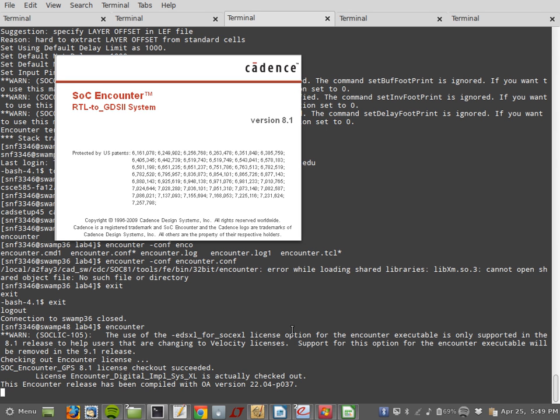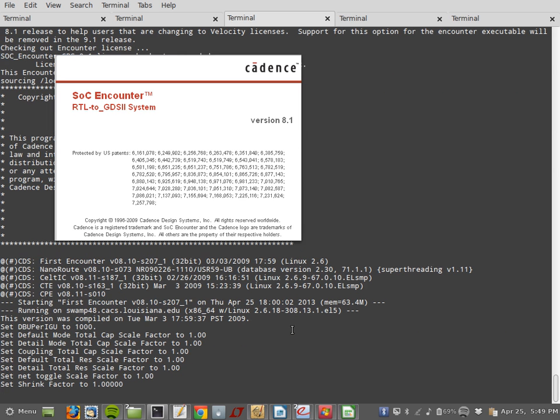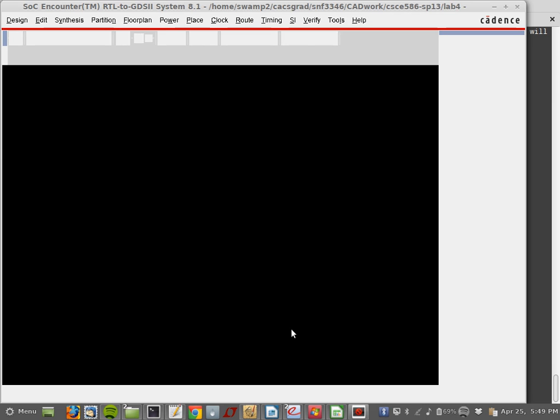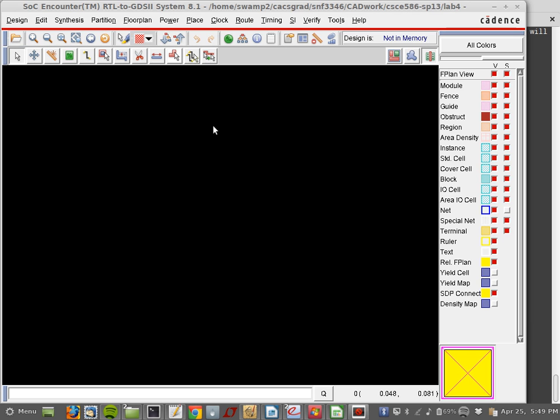If a different tool tries to compile or synthesize the same fragment of code, will the code be interpreted in a different way or the same? If I use Encounter or I use Cadence? You'll probably get different netlists, different circuits, but they'll do the same function as your Verilog code. And it's quite possible I will get different performance. Yeah, of course, because they use different optimization techniques, different algorithms to synthesize.